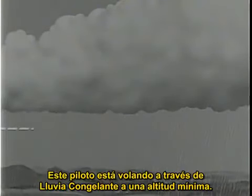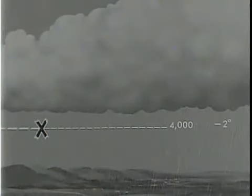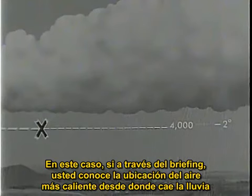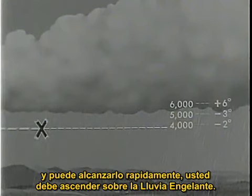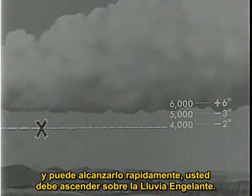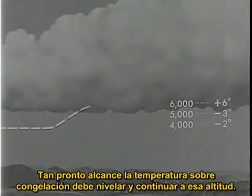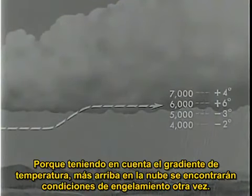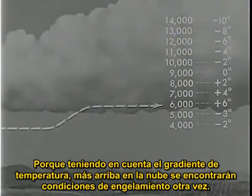This pilot is flying through freezing rain at a minimum altitude. He is becoming badly iced, but does not have adequate terrain clearance to descend safely. In this case, if from your pre-flight briefing you know the location of the warmer air from which the rain is falling and can reach it quickly, you may climb out of the freezing rain. As soon as you reach above freezing temperatures, you should level off and proceed at this altitude, because applying the temperature lapse rate rule, you know that higher in the cloud, icing conditions will again be encountered.